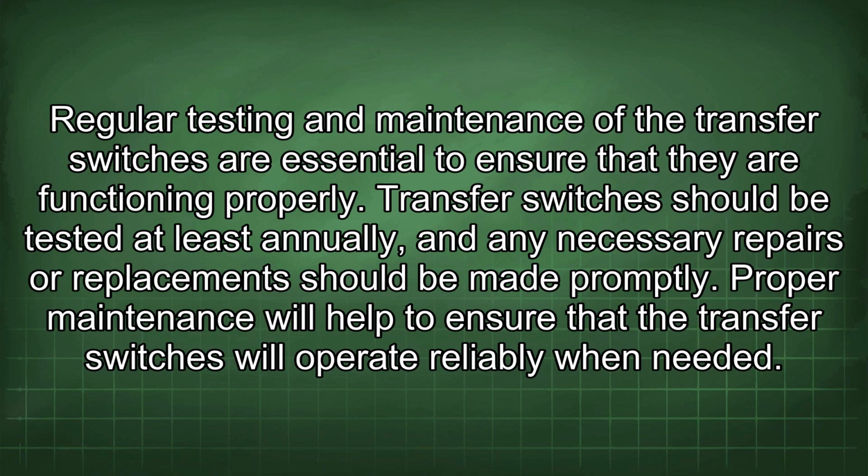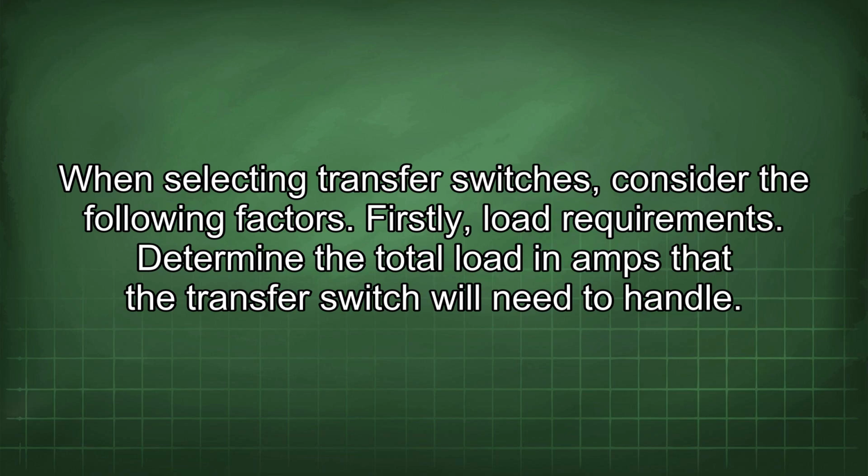Transfer switches should be tested at least annually, and any necessary repairs or replacements should be made promptly. Proper maintenance will help to ensure that the transfer switches will operate reliably when needed. When selecting transfer switches, consider the following factors.